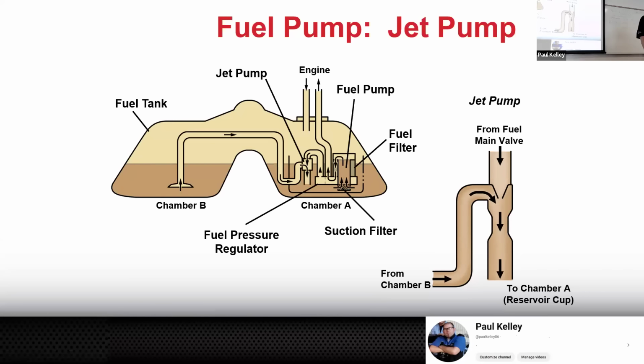I'm for a number of reasons, but if it's a jet pump, it's going to basically be immersed in it and it's going to send it up. Sometimes these will actually have two fuel pumps. And sometimes they'll have a fuel pump on one side, but they'll need a sending unit on the other side to measure how much fuel is in the other side. These types of complex shaped fuel tanks kind of suck, to be honest, but it is what it is.